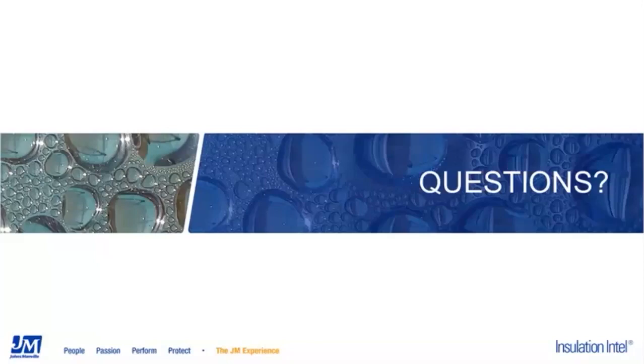So the first way to prevent corrosion is to keep water out. If water does enter, people get worried about there being nasty ions in the insulation, like chloride ions, that could exacerbate the corrosion. But if water's getting in, it's coming from the environment, which is just an inexhaustible source of nasty ions, including chlorides. So the real key is to prevent water from entering the system, which is easy to say and hard to do.